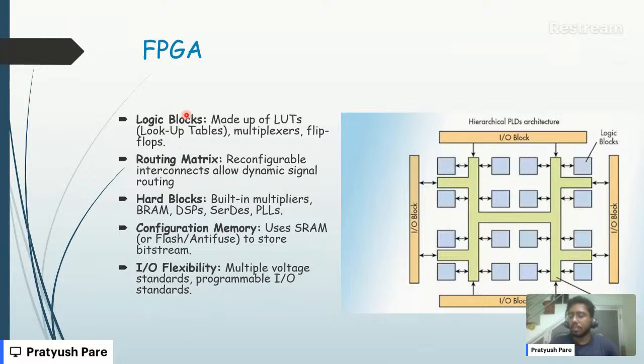That's where FPGAs come into the picture, but they are relatively slow. ASICs come in where we know the direct functionality we want and we stick to that for the lifetime of the chip, but we need very high performance and very low power usage compared to FPGA. That's where ASIC comes into the picture. I hope this clears the question, Ambika.